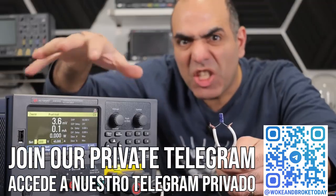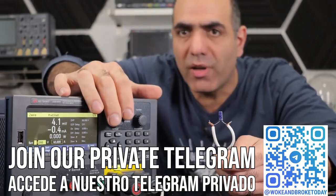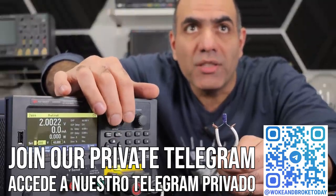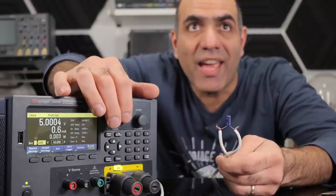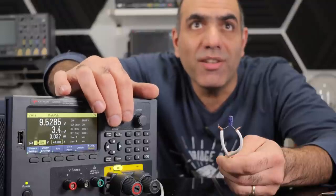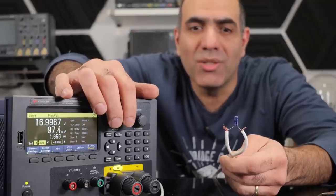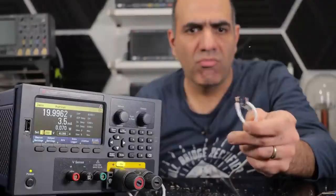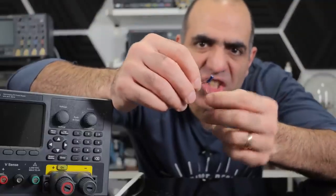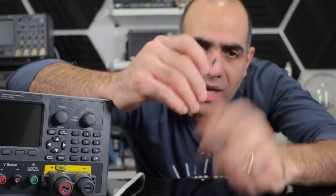I have a brand new 60 volt 40 amp power supply and my capacitor is rated for 16 volts, but I place it in reverse polarity, and if I increase the voltage, at some point it starts conducting current and the capacitor will slowly heat up. You see? Oh, there you go. It's starting to conduct. It's almost 1 watt through the capacitor. Oh, I didn't even see it bulging. I guess it's like a pressure cooker. The dielectric gel in these electrolytic capacitors boils and the pressure builds up until it blows up.